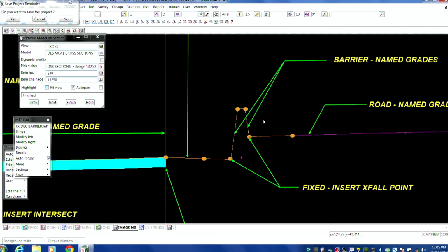So that's what this ends up being. So I can now pick two strings on the layer called construction, without even seeing those strings. I know they're part of my design, and I can nominate those two grades because I need those two slopes on the barrier to find out where this intersection is and where that intersection is. And that's the beauty of the layers, being able to create something that you're using as a construction process, in this case to get two named grades, but I'm never going to see the strings. They're part of my design though.